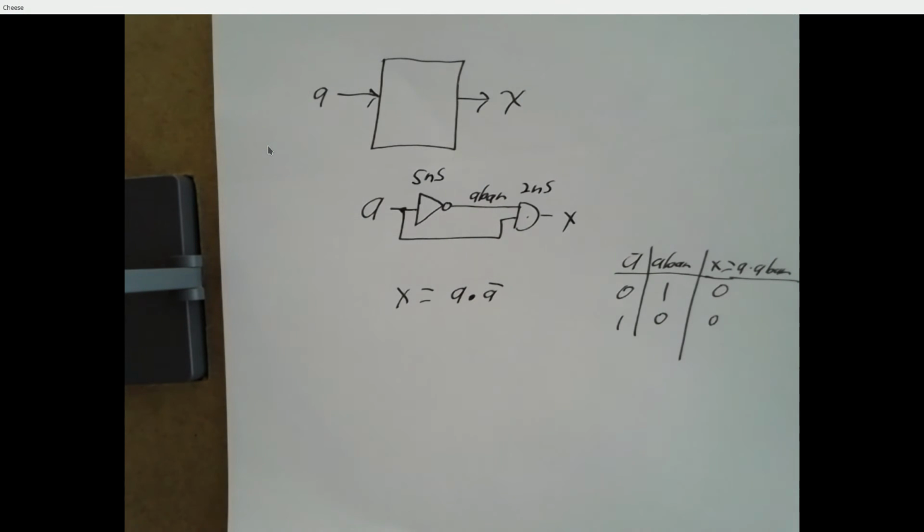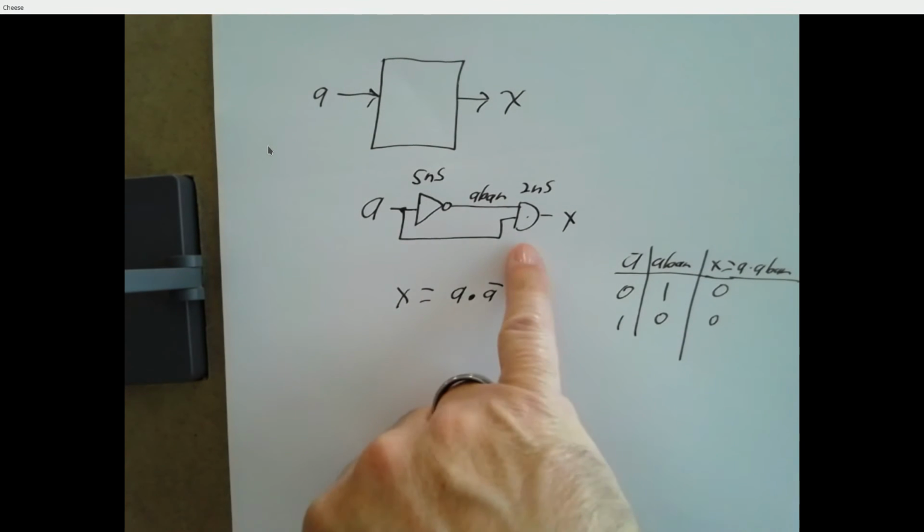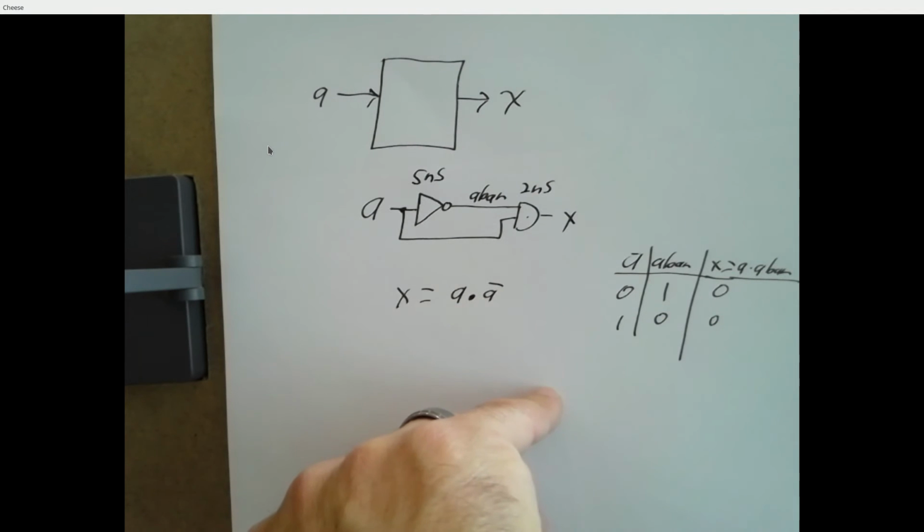So now we've got something like this. 2 nanoseconds here, 5 nanoseconds here. And remember when we talked about timing diagrams, we talked about glitches, we saw that if we build this kind of circuit, sometimes we get a glitch. Sometimes the output's not 0.